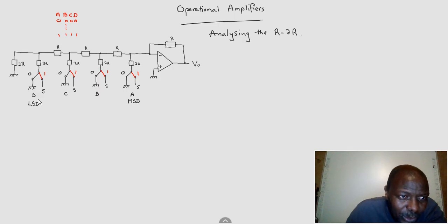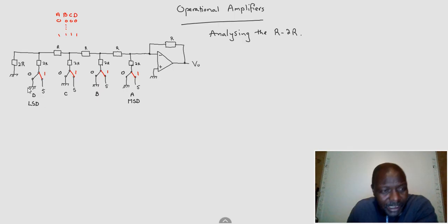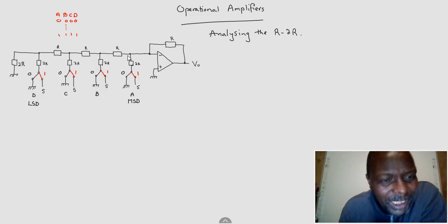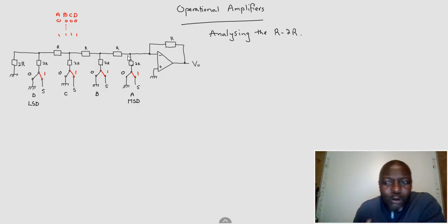All right. So what we want, therefore, is our step, which is D. We want to calculate our step voltage here. How do we do this? Remember, this circuit has 4 supplies. This is a little complex scenario. So to analyze this, it is best if you go back to our basics.